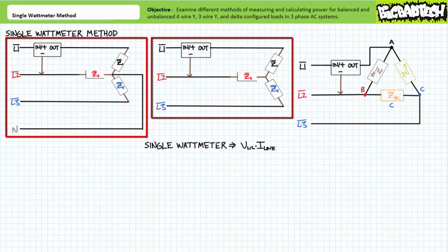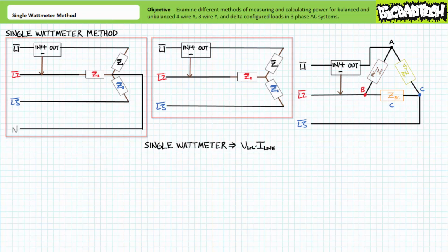In the case of the balanced Y configurations, the ammeter portion of the wattmeter appears to be reading current correctly, as line current equals load current in Y configurations. However, loads in balanced Y configurations don't directly experience the line-to-line voltage, but rather a smaller portion of it. Taken in isolation, this wattmeter's reading is extremely suspect since it's artificially inflating voltage.